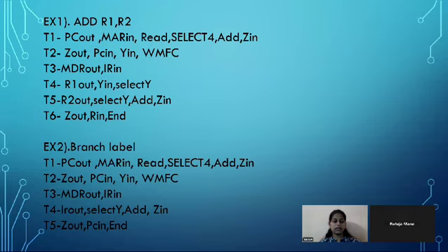In the last cycle: Z out, R1 in, end. The result from the Z register is placed on the bus and the result is loaded into register R1, and the end shows that the operation is completed here.